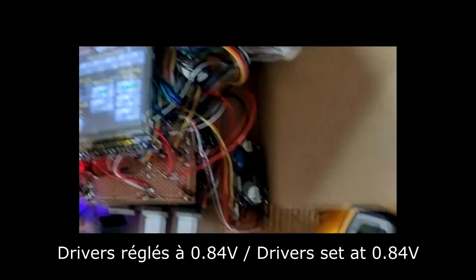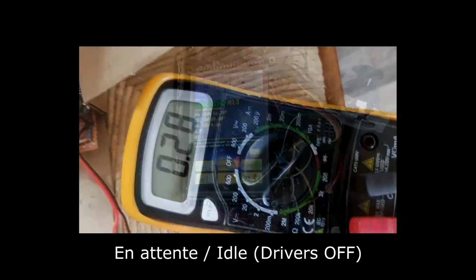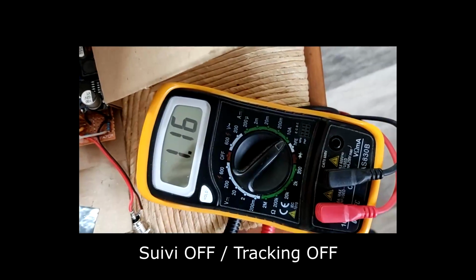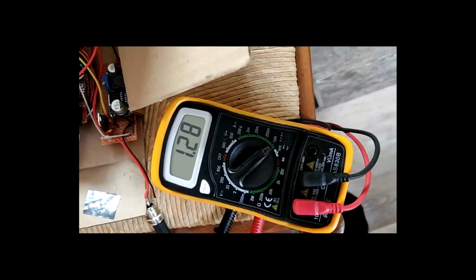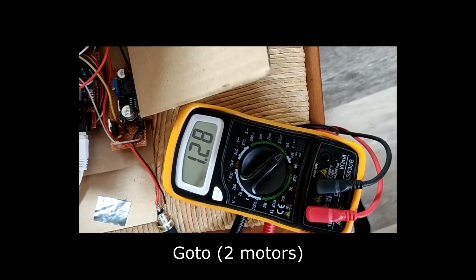Let's talk about power consumption now. At first the drivers were set at the maximum value, and at idle we observe a consumption of 0.3 amperes. Here with the stepper motors on and no tracking, with the GOTO 1 motor, with the GOTO 2 motors, this is a little bit more, when tracking on RA.